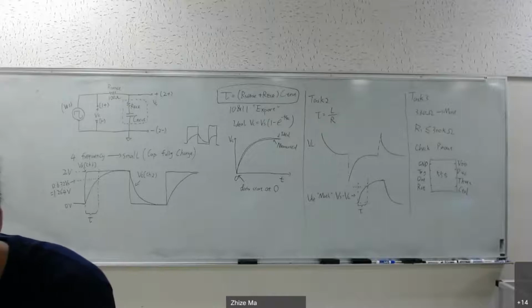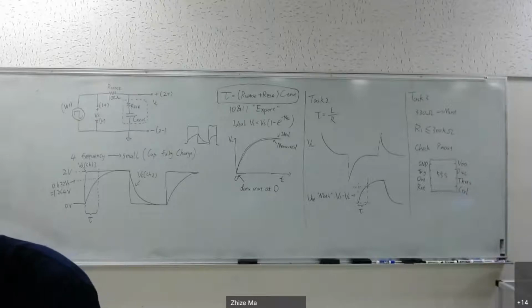You're going to use that equation to calculate the R1 and C1 values in this task. If you're not sure whether your answer is right, please check the introduction video. That video shows you how to do the calculation, and you can just follow the equation the video used. First of all, you need to calculate the R1 and C1 values, and the R2 value is already given. It's a 10K ohm resistor.